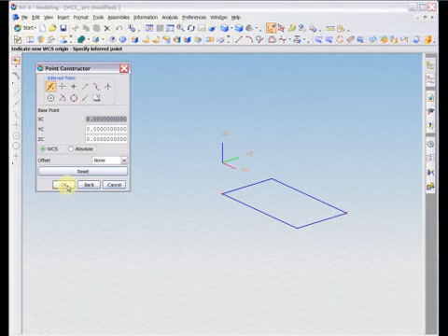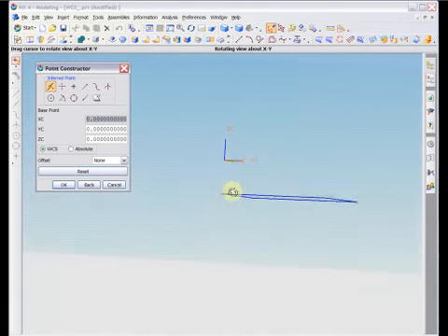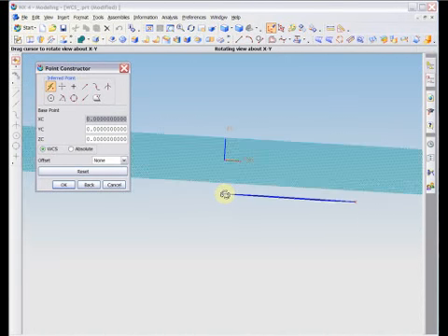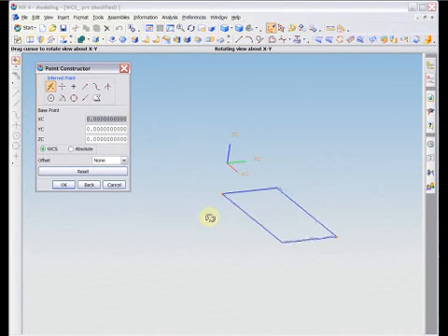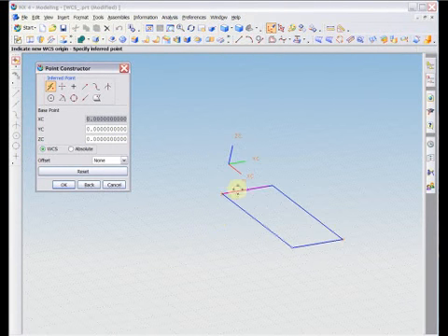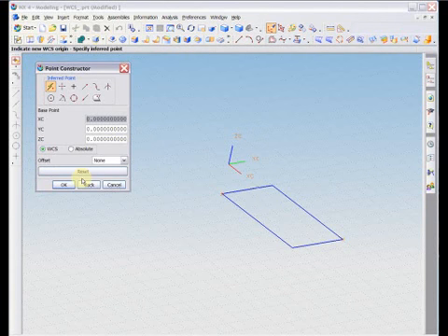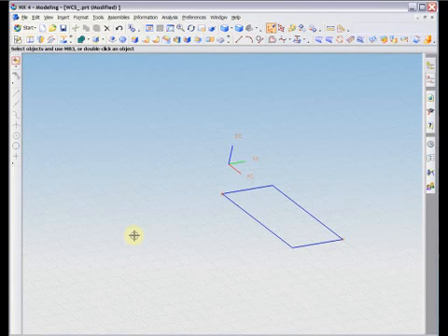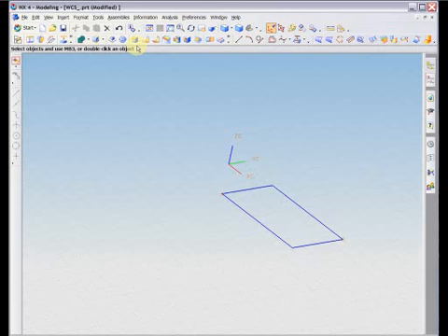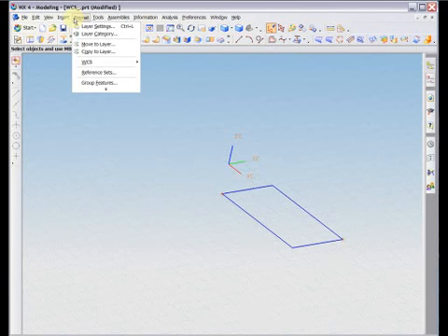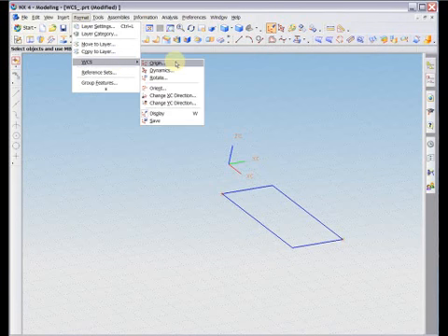Note that these changes are always applied to the current coordinate system. You can tell this as the C's in the XC, YC, and ZC coordinates stand for current. If you want to restore the coordinate system back to the absolute coordinate system, we can simply go to Format, WCS, Orient, and choose the absolute icon.